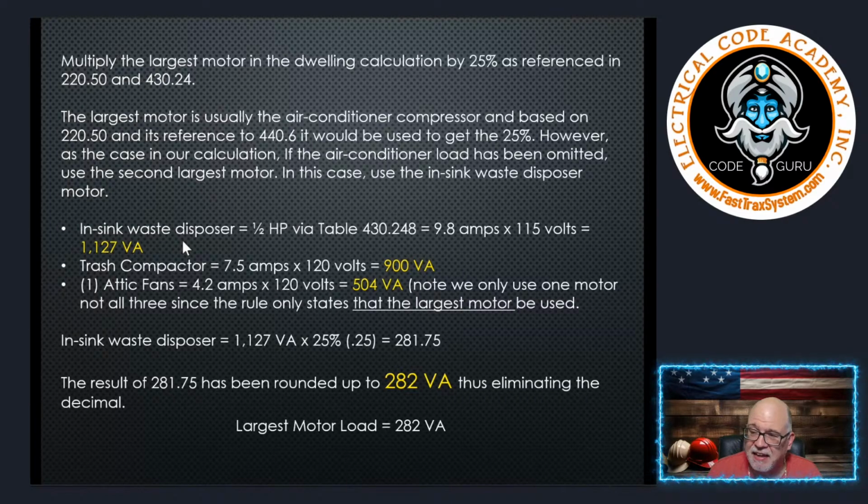So I'm going to take that 1,127 and multiply it by 25%, or 0.25. I always like to break things down into decimals. It makes the math easier. That means it's going to be 281.75, and we're going to round that to 282. That is my 25% for the largest motor contribution.